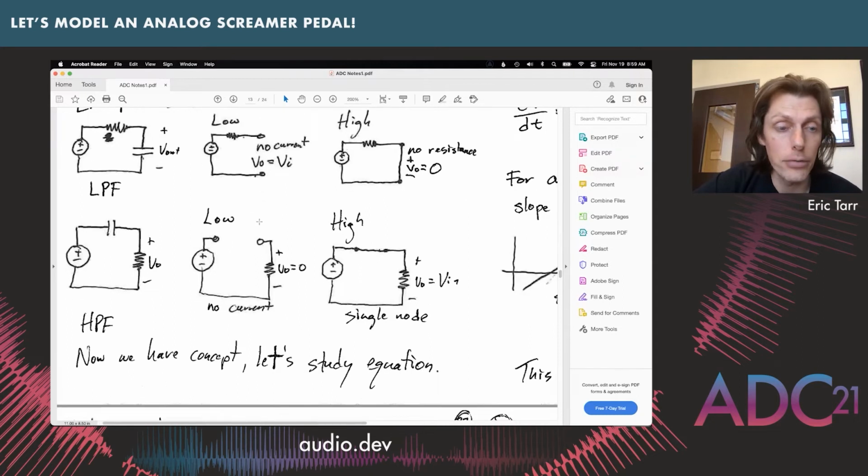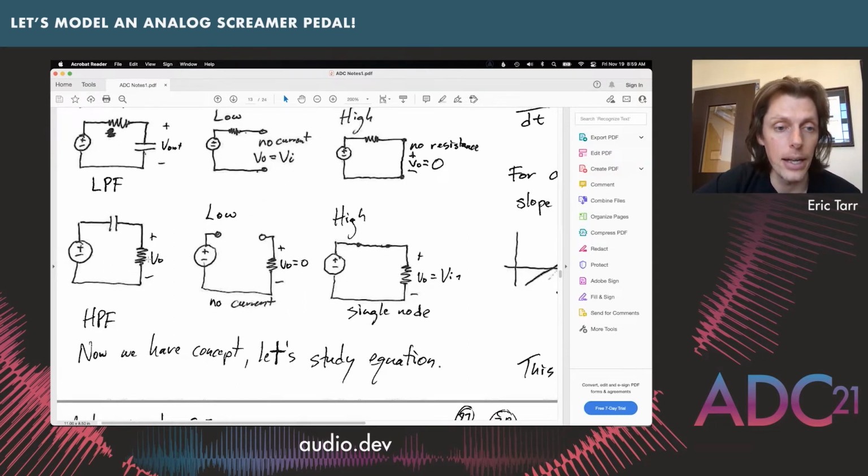In the case of rearranging our capacitor and our resistor like this, our capacitor acts as an open circuit for low frequencies, and in that case, there's no current that's going to flow. So when we take the voltage across this resistor, there's nothing left over. So we have nothing for low frequencies at our output.